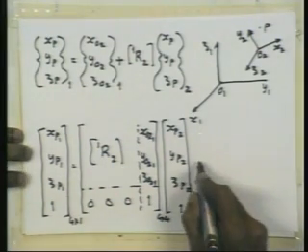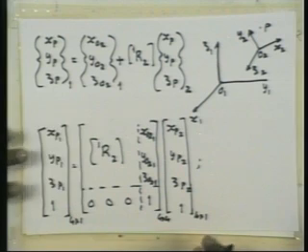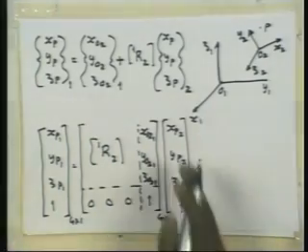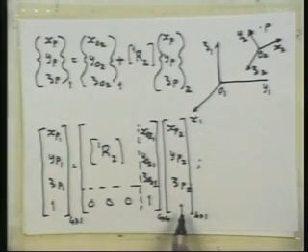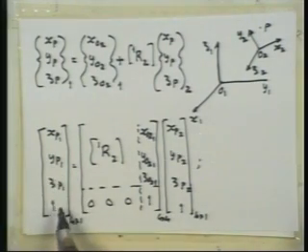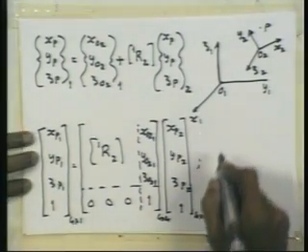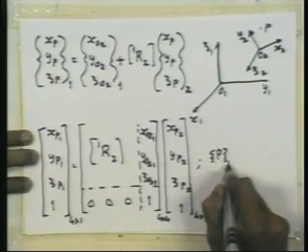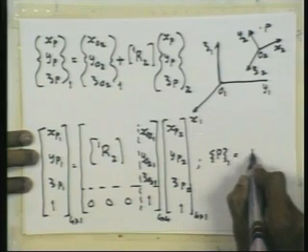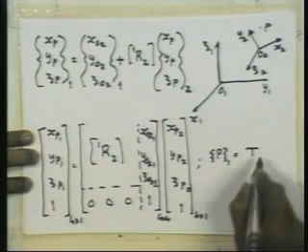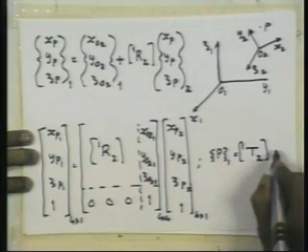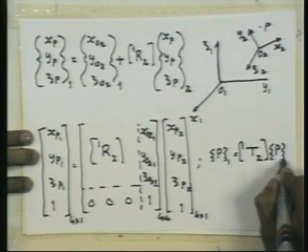Now remember this transforms the locations of points. So we have this as the local coordinates of the point and this as a global coordinate of the point. So let me call it P in coordinate in reference frame 1 is equal to this transformation matrix, which is 4 by 4 taking 2 to 1, and P in 2.